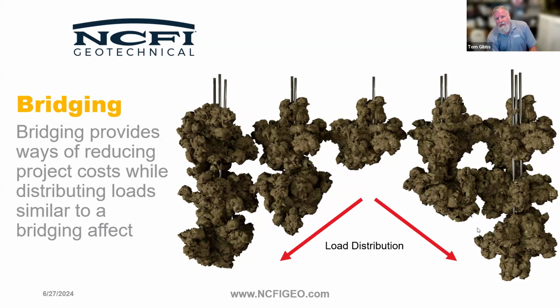It can be effective. The biggest area I see it used is in post-construction. There are a lot of cheaper methods for pre-construction, but once you've built the building, it becomes very difficult to install solutions like wick drains, because you'd have to tear up the whole floor to do the work.